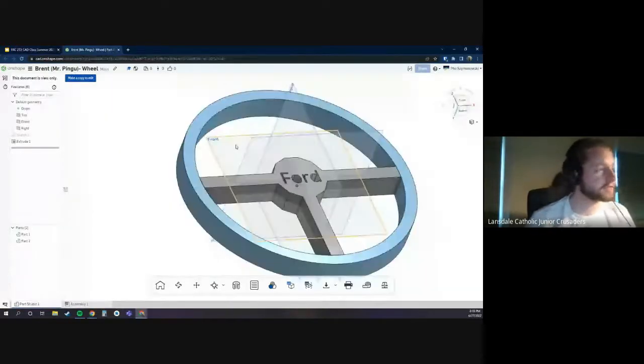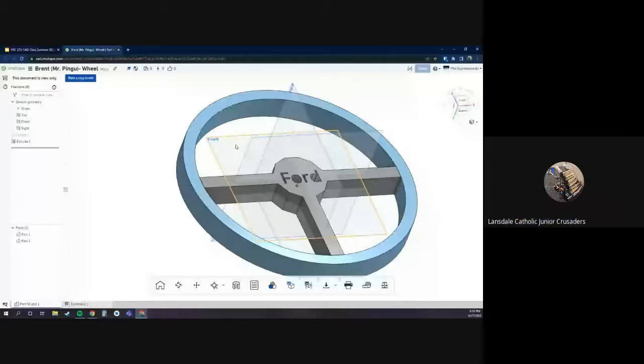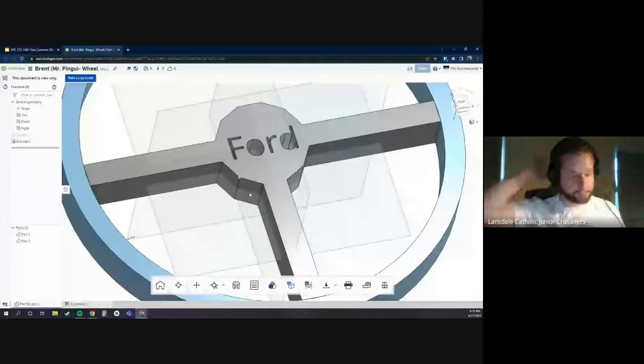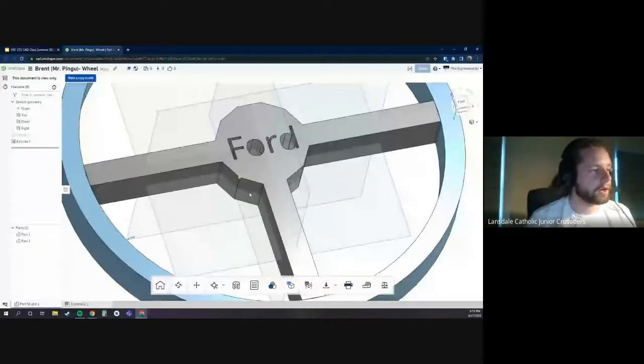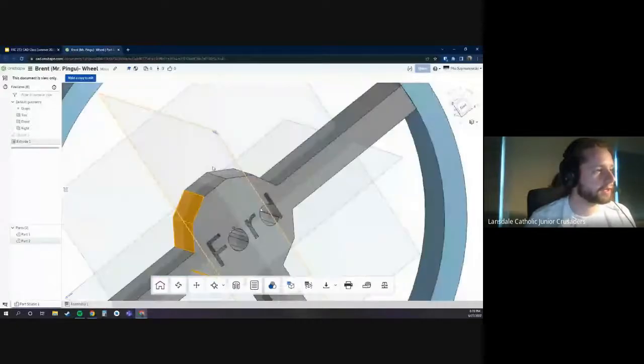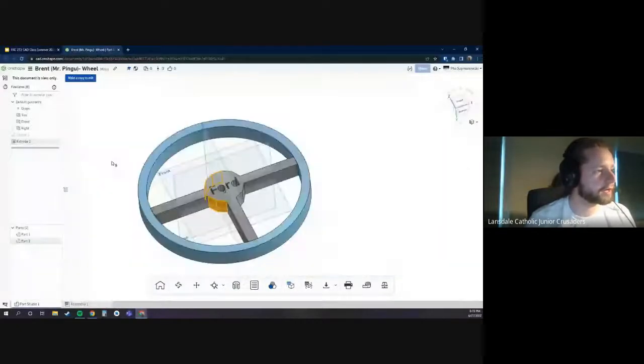So interestingly enough, you did this all with one sketch. You created both of these parts because you actually have two separate parts here, which is cool. So you did it with one sketch and one single extrude feature. This is a good example of it in Onshape. You can make multiple parts with one sketch, like a geometry pattern on the inside, or an octagon or nonagon or something for this inside shape, right?